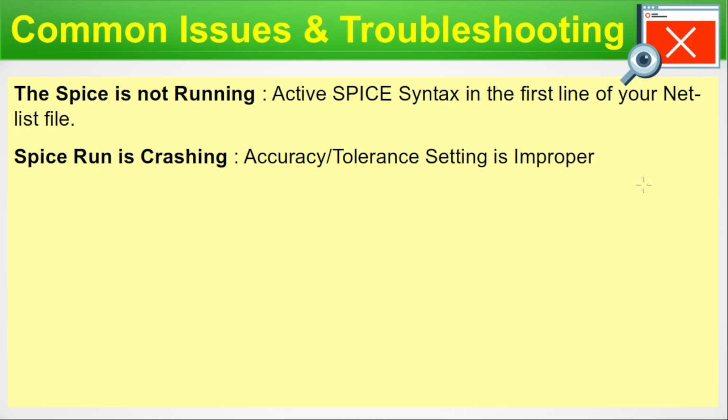And in addition to these particular SPICE options, there can be some tool-specific options that may vary from one vendor to another. Even if you have three different SPICE simulators from three different EDA vendors, they might have additional tolerance or accuracy settings defined on their own. For that you have to consult their tool manual, not the SPICE language. The SPICE language does have some impact, but on top of that, when the simulator is running, they can have their own options to deal with difficult situations. You have to be aware of them and use them properly.